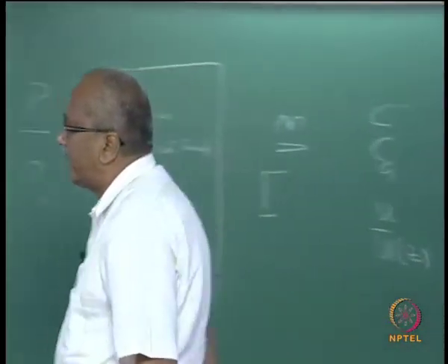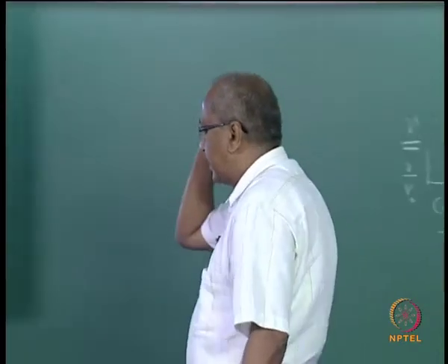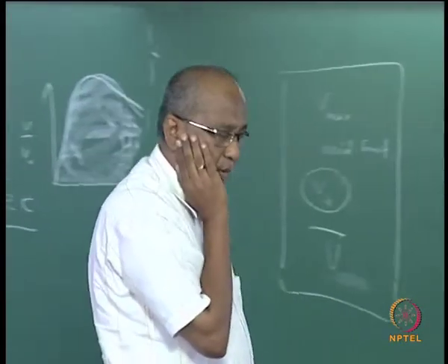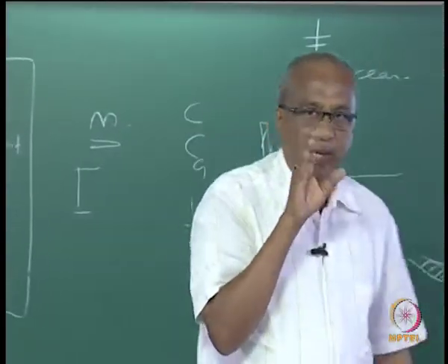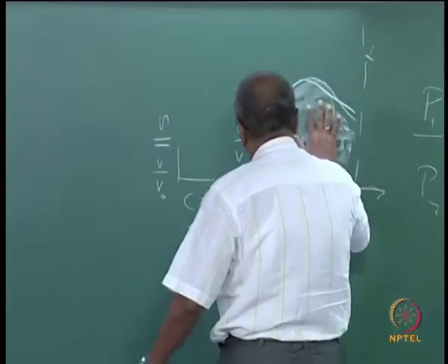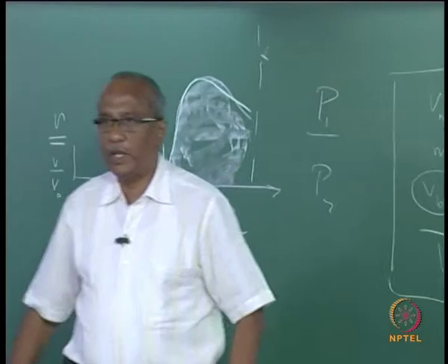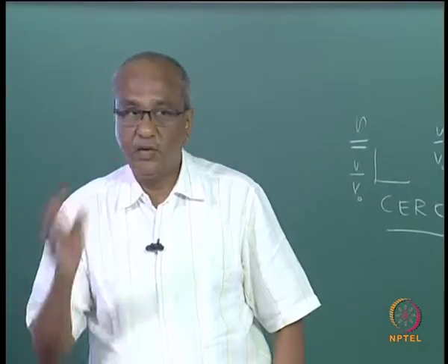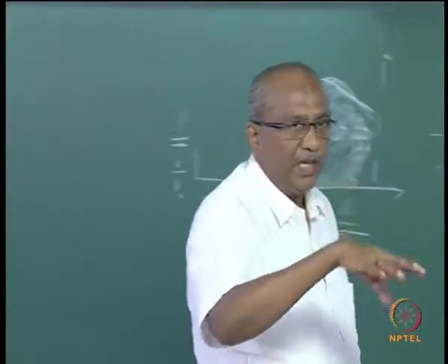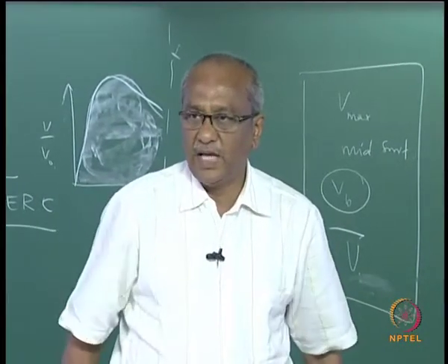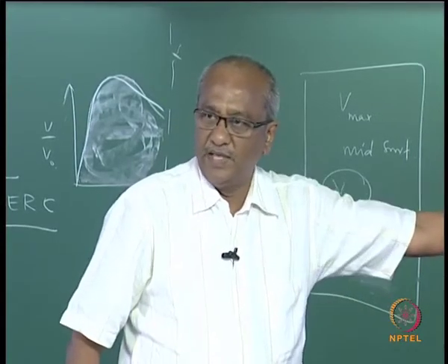Now what we are trying to do is understand how the distribution of longshore current velocity would look like. As I have told you the principle, once you get the distribution of the longshore current velocity, you can integrate and get the total sediment transport rate. That is, you have to equate it to the total immersed volume of the sand. That is what we have already seen.